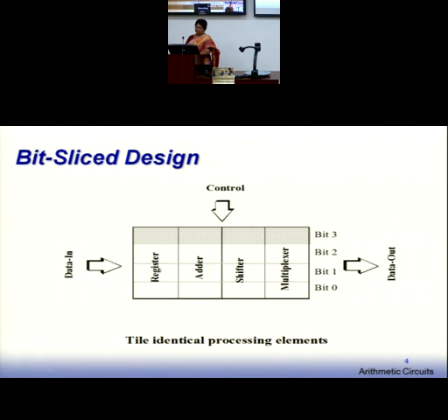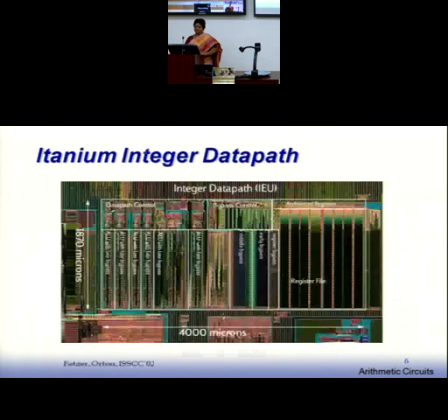Now you can have a change here. You can have a control coming from below, a data in here, a data out here. But more or less, it is going to be an architecture where you fix one side for data in, one side for data out, one upper or lower maybe for control, so as to have easy layout of the wires, easy layout of the interconnections. And then you can easily configure which is coming from which side. Ease of design. So normally we get a design of this nature.